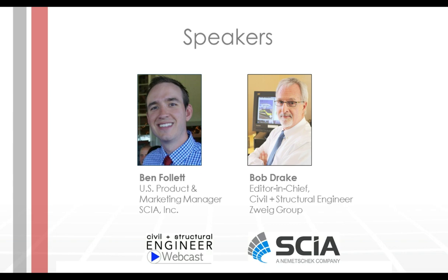More specifically, though, we do some material-based nonlinear analysis, plastic analysis for ductile materials. So plates of aluminum or steel or cold form steel or other metals. We have a module that allows those materials in those slabs to go from elastic to plastic in that sense. For concrete, we have some stuff for cracking, and that's not really nonlinear, but for cracking and nonlinear analysis and cracking with reinforcement. And so all of those are different ways to take in the nonlinear analysis in those materials.